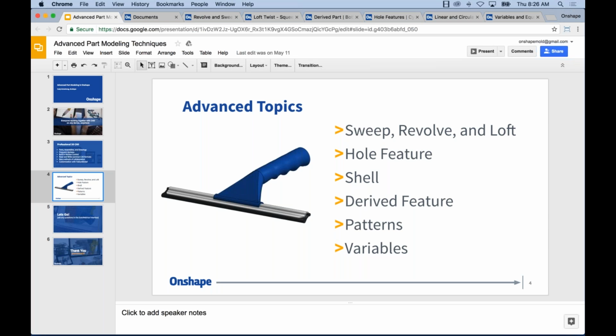And I would say breaking things up if necessary, if you're talking about multiple parts. Avoid the really complex shapes. I shouldn't say complex, I should say a lot of faces. Heavy patterns tend to do it, and threads tend to do it. Anything that would generate a lot of faces in a single command tends to take a long time to rebuild. So just some general advice. I would do a search on the forum if you're really interested in the details. There was a whole forum thread. I responded to it. Alana, a member of our dev team, I believe, also responded to it. A very good thread.